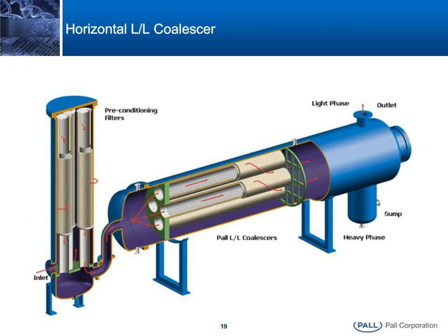Particulate removal happens in the pre-filter, and the horizontal orientation of the liquid-liquid coalescer takes the flow in an inside-out flow direction in the coalescers, forming the droplets passing through the medium until they are large enough, in this case, to settle out due to gravity, traveling to the far end of the housing until they settle out in the boot or the sump at the bottom of the housing at the far end.